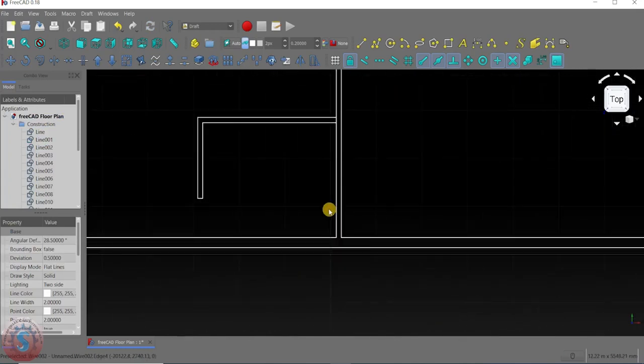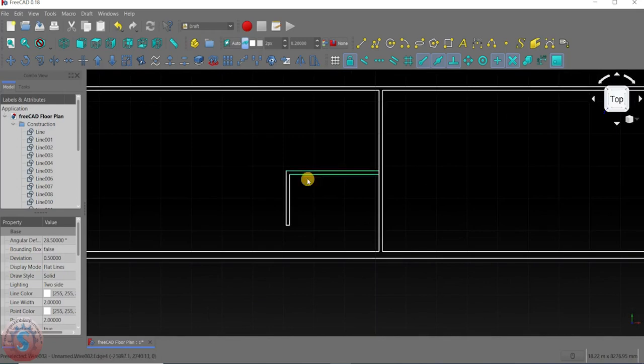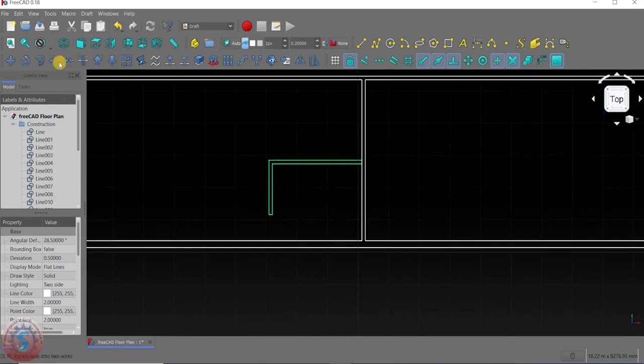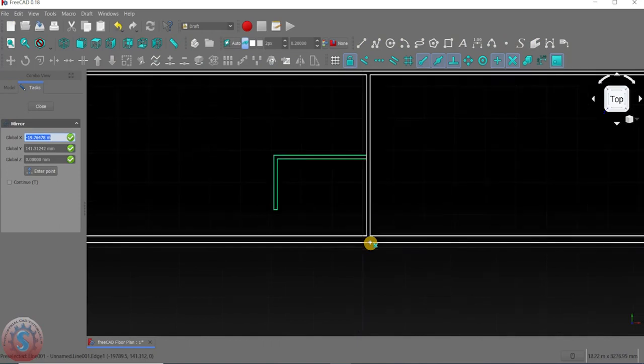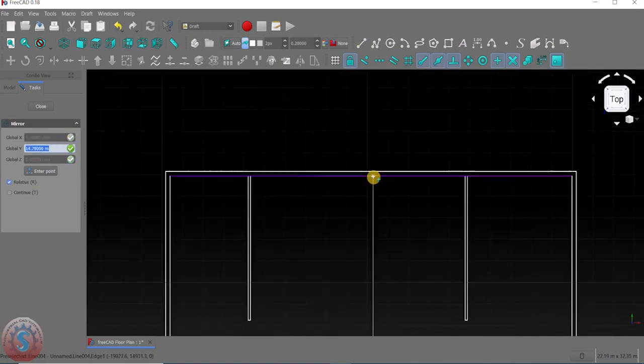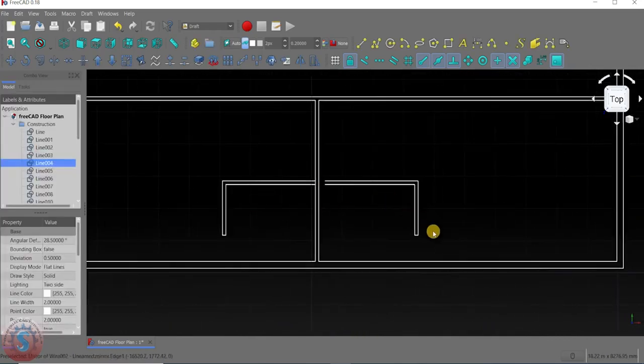You want to mirror this line. How to mirror this I will show you. For example, I'm selecting all of the lines by using the control. Here you can observe the mirror command. Here the mirror option is there. The mirror command is MI, and click on the mirror option. Already the center points are there. You can also, by using these center points, first and second point, see the mirror is created simply.